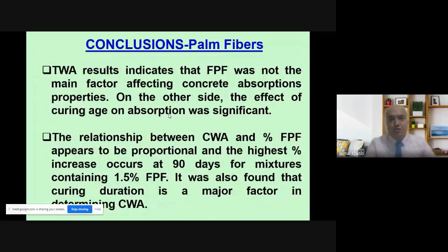Total water absorption indicates that FRP was not the main factor affecting concrete absorption. On the other side, the effect of curing age on absorption was significant. So if you look at the water absorption at early age, it is not the same as the one at later age. Again, I want to stress the point on proper compaction.